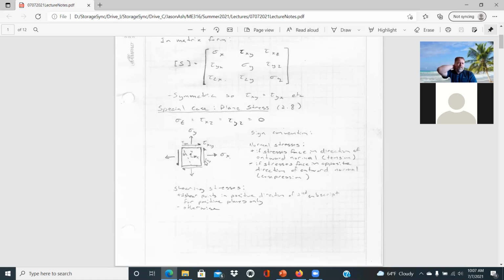That's really the whole idea of stress and strain transformations: the orientation of the stress element with respect to the X and Y axes. This is the start of that discussion, where we have an angled cut at some angle theta, and we want to know what sigma X prime and sigma Y prime look like on our rotated axes.